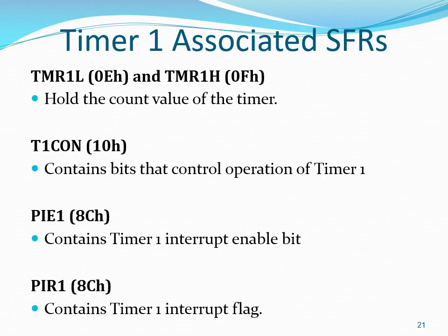T1CON contains bits that are used to control the operation of the timer. PIE1 contains the interrupt enable bit for the timer overflow interrupt. PIR1 contains the interrupt flag for the timer overflow interrupt.